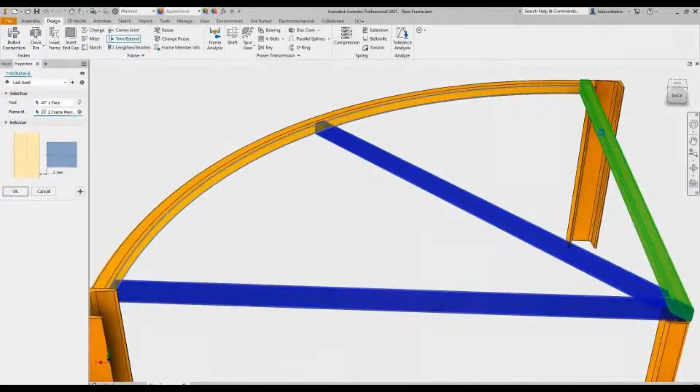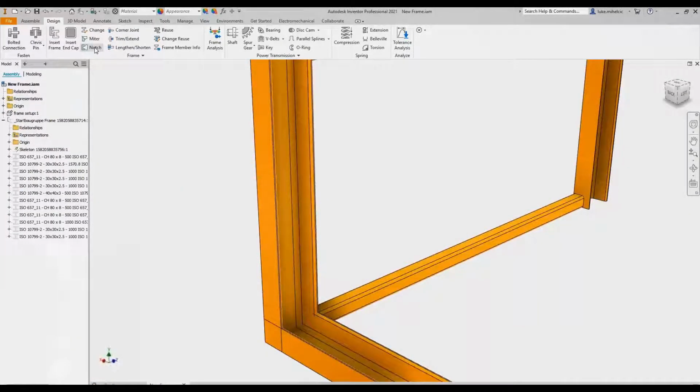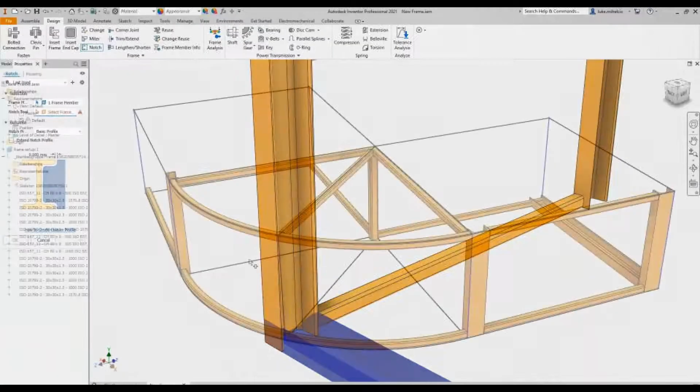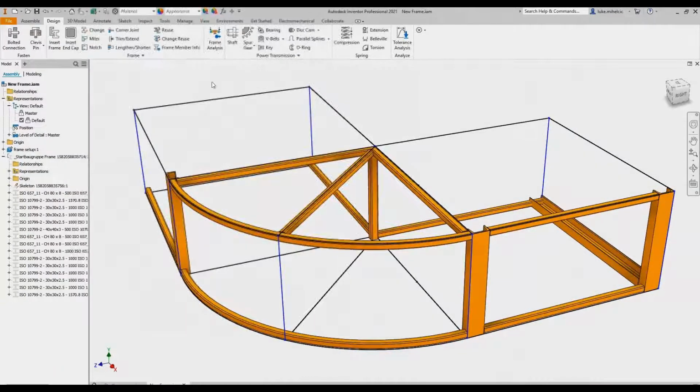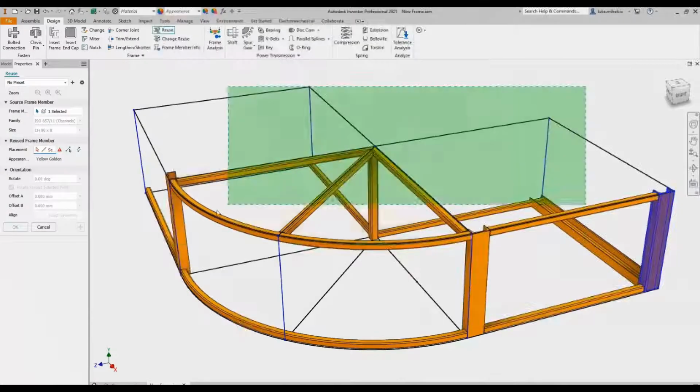There are 3 new display controls in the property panel that set the zoom and view orientation. So one of them sets the view perpendicular to the frame manipulators, zooms to the frame manipulators, and returns the display to the initial view. The apply appearance to part option is added to the advanced settings menu for insert, change, reuse, and change reuse.